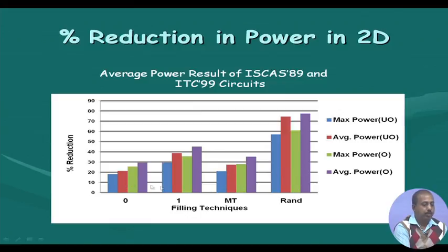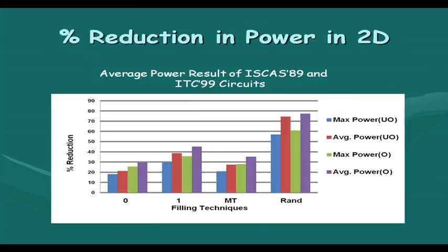there, but you see for zero fill and empty fill, these two cases, improvements are not that high, because empty fill actually reduces those scan transitions, and for zero fill, in most of the cases of the logic gates that we have, if we apply a 0, one of the inputs is 0, the output does not change. So that is why these transitions are less, and the flip flops also normally, if it is 0, are not going to have a lot of transitions. So this way, for zero fill and empty fill the transitions are less. Of course, this is very much logic family specific, maybe the technology family that has been used in getting these results, where 0 is consuming less power than 1. For random, of course, there are a lot of improvements.